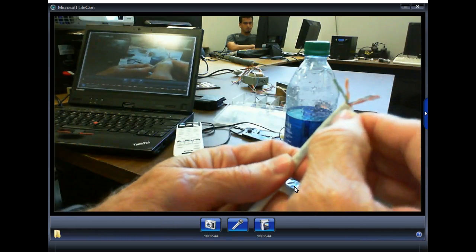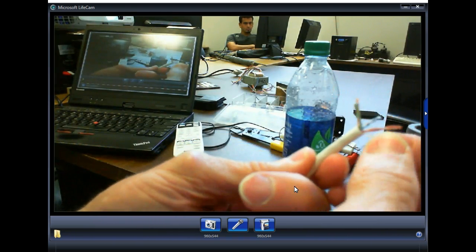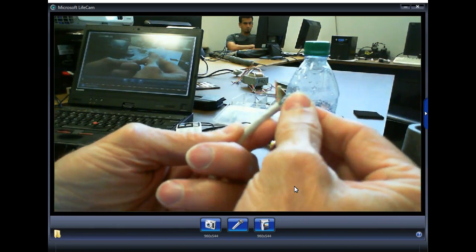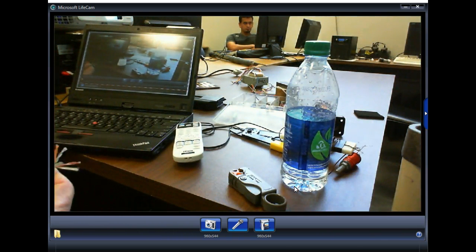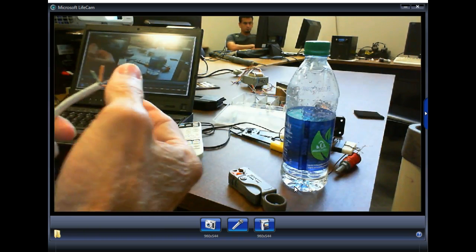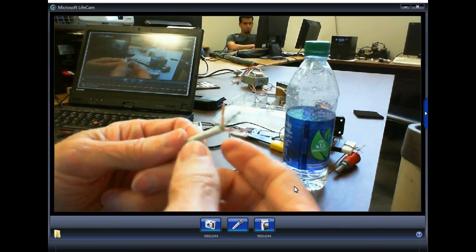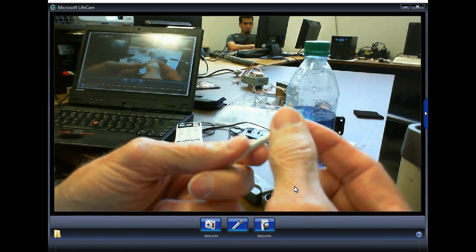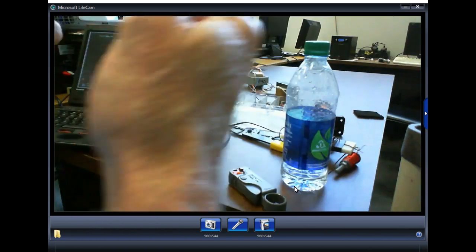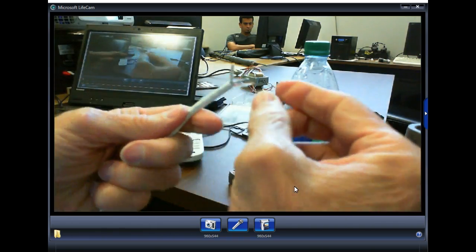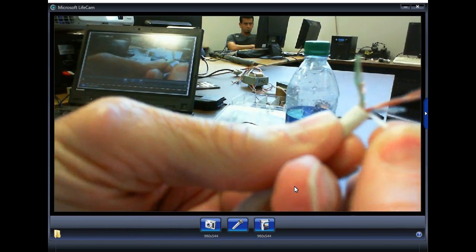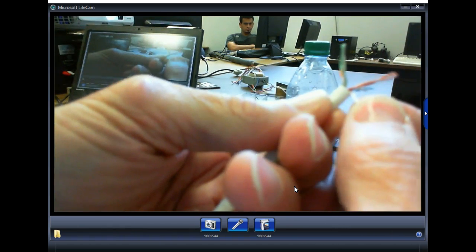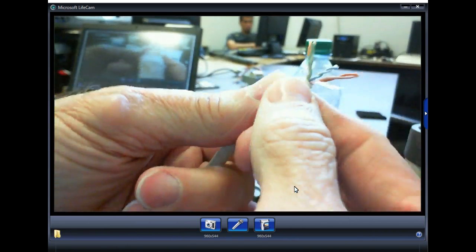It's got a nylon cord that runs in here that adds physical strength to the cable, so we can pull the cable. Pulling the cable is a technique of getting cable through conduit. We run the conduit, and we run what we call a cable puller through it, which is kind of like a wire. Then we connect it onto the cable and pull it back through the conduit. The problem is, if you put a lot of stress on a very small conductor, it's going to elongate on you, right? And that's going to change the gauge. So a lot of these cables that have really small conductors will have either nylon or something in there that allows us to pull it without putting stress on the wire. That makes sense? So that's why that's there.